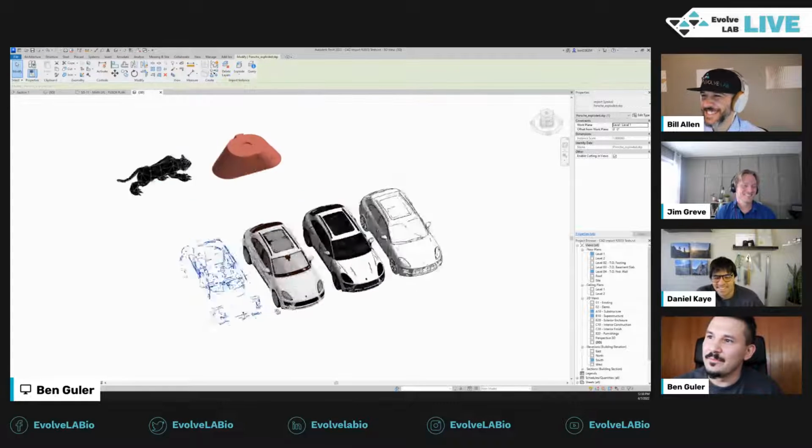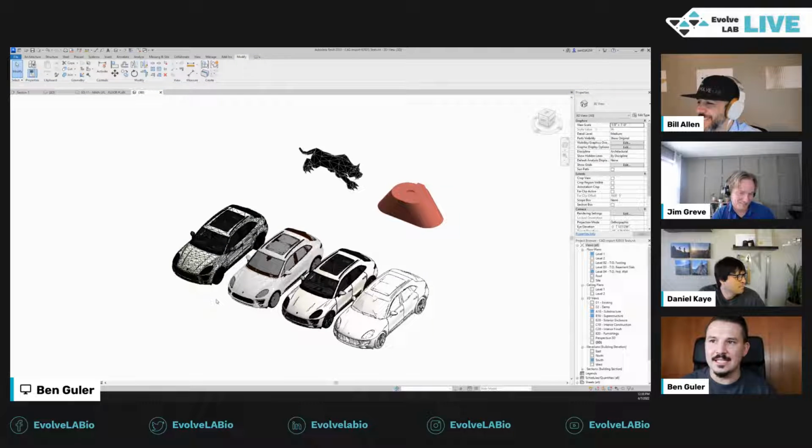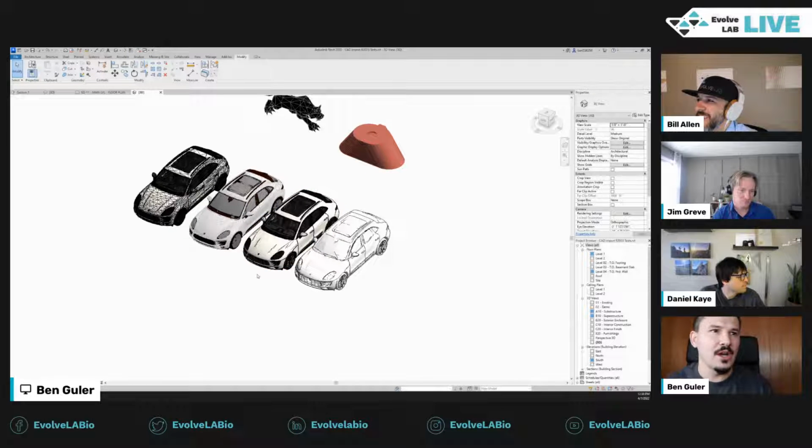Basically, the next part of this is I tested that they've improved the importer for meshes, which I thought was really cool. But I did find some limitations. It seemed like mostly you have to use the OBJ importer. I was not able to replicate it with DWGs, DXFs, or SketchUp imports.